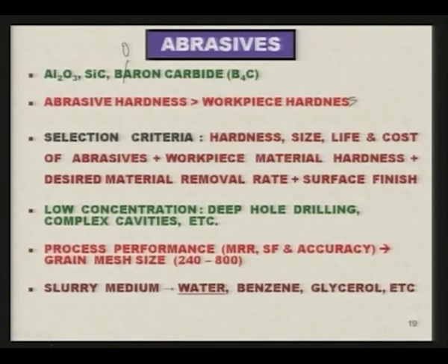Slurry medium or the abrasive carrying medium normally selected is either water, benzene, glycerol, etc. Especially a low viscosity liquid like water is recommended, so that it can reach the fine details or complicated shapes easily.